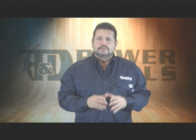The circuit breakers we've investigated so far are just two of the many types that you'll find in switchyards. By looking at SF6s and OCBs, we've seen two very different ways that circuit breakers can extinguish arcs when circuits are opened and closed. On the other hand, disconnect switches don't need many special features for quenching arcs. Circuit breakers do all of the actual switching.